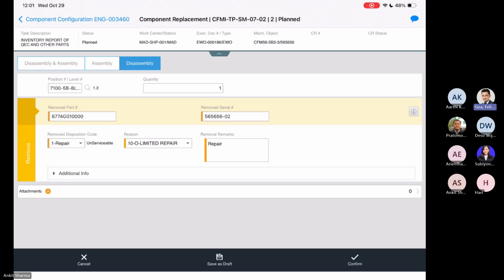So basically, you have a child work order set up. For that child work order, just like how we did planning for an engine work order, where you had the due list and the applicable tasks you picked from there. The moment you have a child work order for your module or your sub-assemblies, go back to the same plan work order screen that you were just looking at, the due list. It will still show you the same applicable tasks, applicable engineering orders. From there you pick, you plan, and you release it, and it comes back to the same place after the CAC.